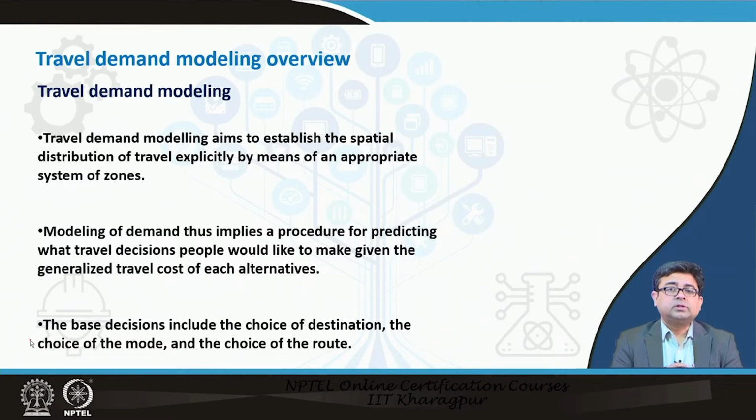When non-commuters, meaning non-office goers, make their trips, you really have difficulty in predicting where they are going, and you need very high data about the land uses and the trip purposes to predict exactly where people are going, so that you provide adequate capacity of your transportation systems to meet the needs of the traveling people.